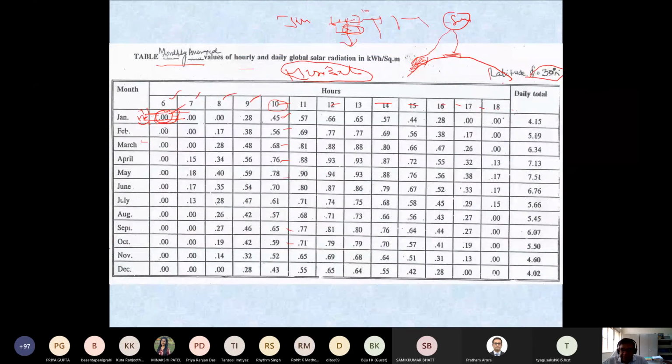Yes. See this table, this is solar radiation at one location. I think I have to design the system on a daily basis. So these are the solar radiations, and I can take the average. These radiations are for 12 days, because it is one day for each month. So I can add them and divide by 12, and I get the average solar radiation available at that location.